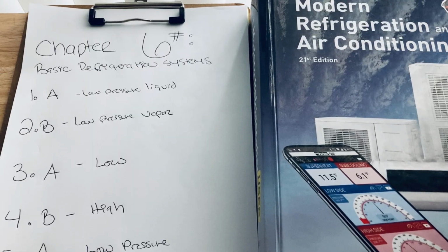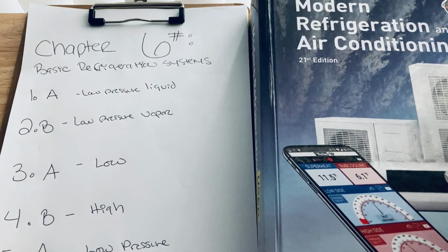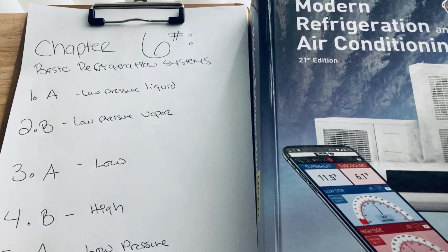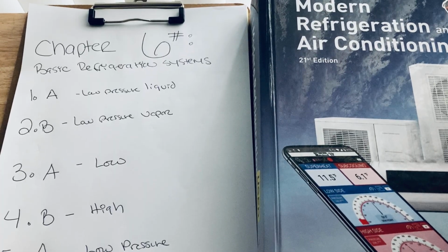A storage tank for liquid refrigerant, we're at 11. We just talked about 2 tanks a couple questions back. A storage tank for liquid refrigerant on the high side of the system is what? That's going to be D, liquid receiver. That's on page 90. So liquid receiver is a tank. The accumulator is also a tank. That's on page 94, but it's on the low side. So accumulator is a tank, but low side, and liquid receiver is a tank, but high side. So the answer is D, liquid receiver.